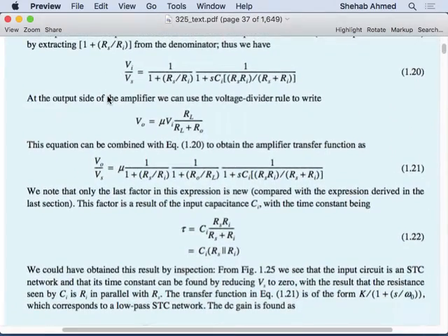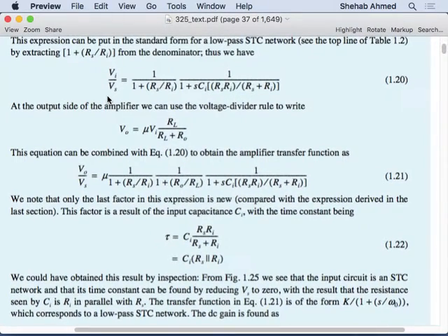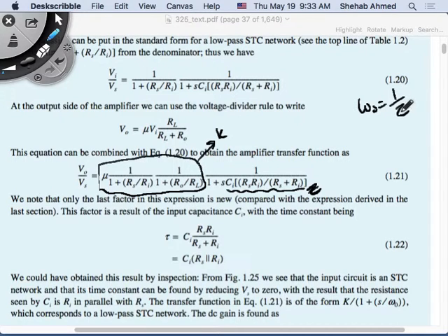So we can go that route. There's a trick, however, right? So we said that this is what will resemble our K, and this is what will resemble our time constant. Omega naught is equal to 1 over tau, where tau is RC, which is 1 over C times the combination of resistors that we have in here, right?